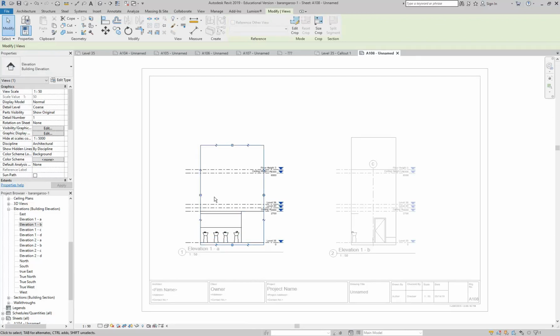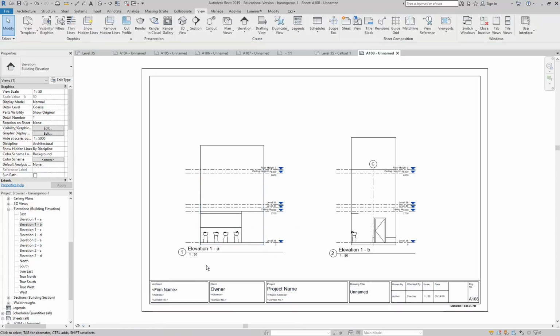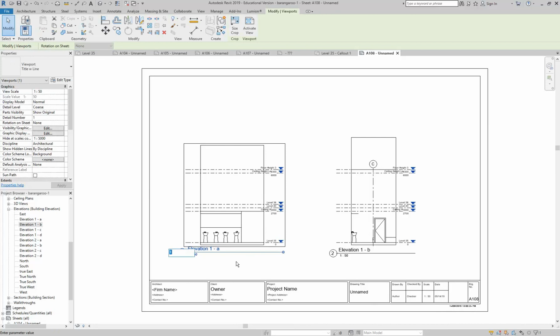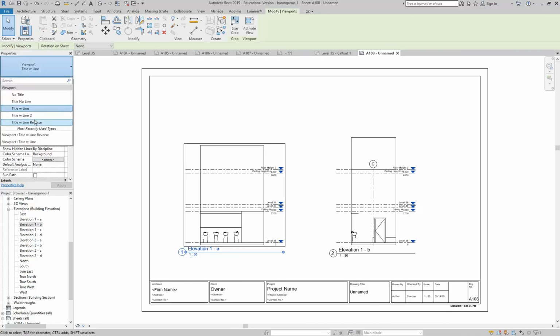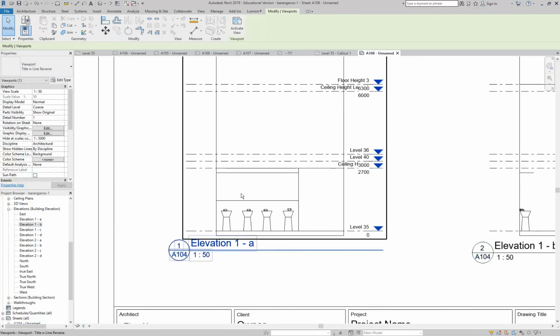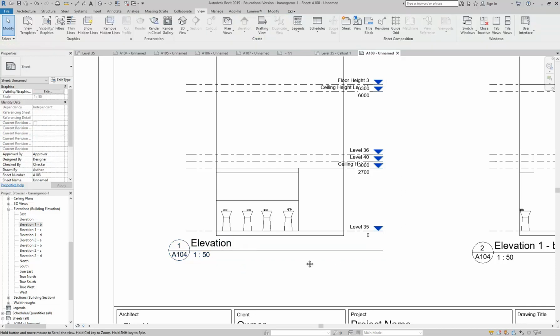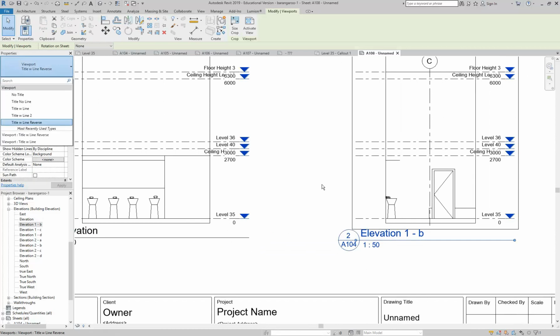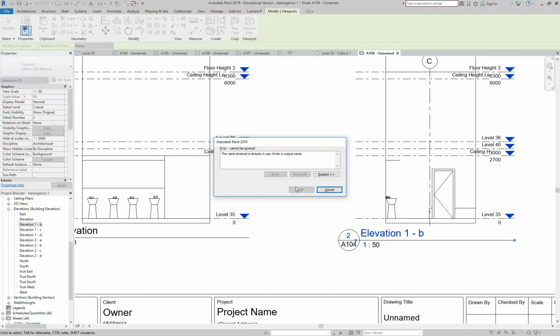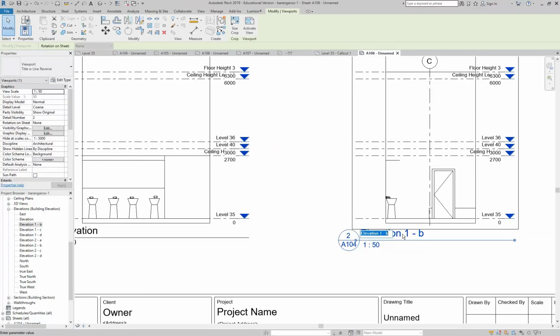And then you wouldn't put in elevation 1A, because the number's here. The number is in the view tag. And we can even put it with the reverse one. That'll work nicely here. So that's the numbering. Putting a number into the title as well just adds confusion. So you could put bathroom elevation, but I always said to people doing my drawings, don't worry. The number gives the reference. So you just need to say whether it's an elevation, a plan, or a section. Or you could maybe say detail section or something like that. But you don't need to say elevation 1 or 2 again.